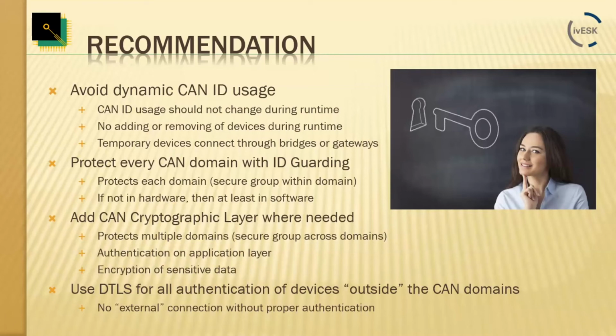Some overall recommendations. Number one, because it makes life for any security measure that we are taking so much more complicated, try to avoid the dynamic use of CAN IDs. I mentioned earlier that we all know in CAN systems that CAN IDs are assigned uniquely.